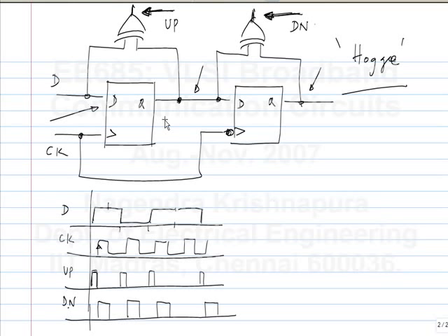But see, if you design something for a certain frequency, it's not likely that it will suddenly start oscillating at half the frequency and lock there. Usually, let's say you are making a 10 gigabits per second receiver. Now you make your VCO oscillate at 10 gigahertz. Of course, you can't make it oscillate exactly at 10 gigahertz. There will be process variations and so on. So maybe you cover for process variations, and also for some mismatch between the transmit and receive clock frequency. So maybe you make it 10 gigahertz plus or minus 10% or 20% or something like that. In that case, you don't have this problem of harmonic locking.